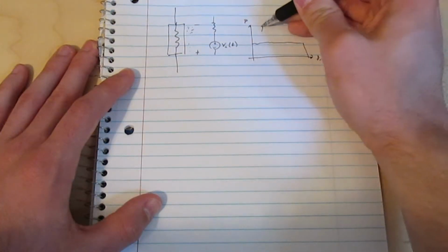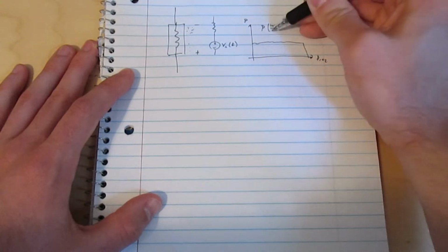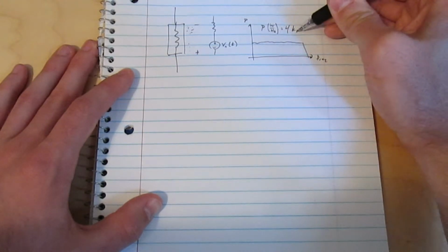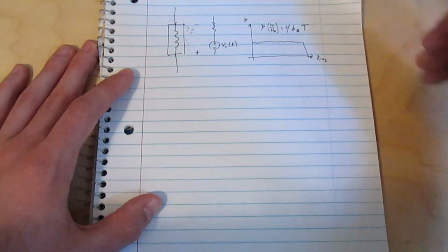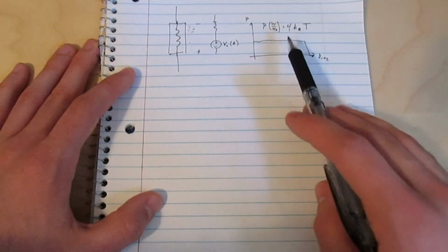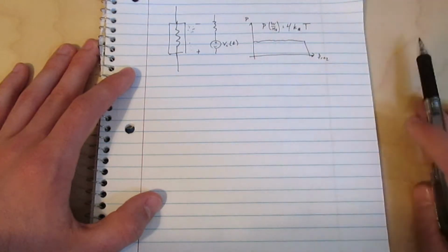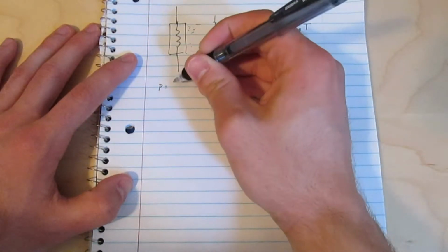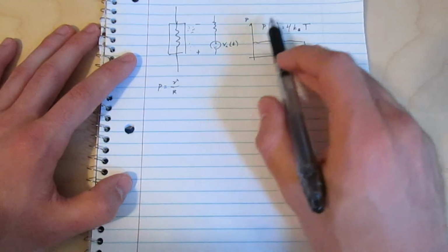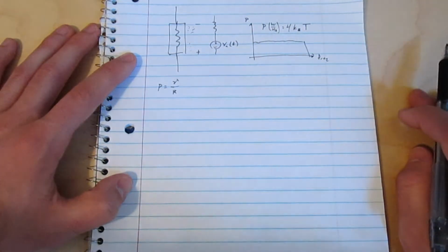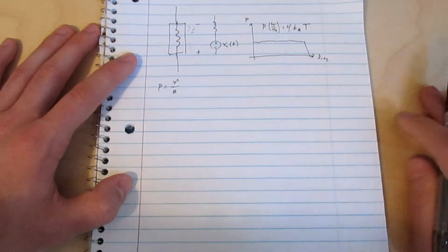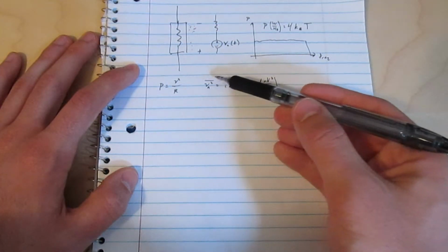And the power density in units of watts per hertz is given by the formula 4 times the Boltzmann constant times the temperature. Now exactly where this formula came from is kind of a long story, one that I forgot a long time ago, but there it is. Since the power dissipated in a resistor is the voltage squared divided by the resistance, we can plug this into our power density equation to get an idea of roughly what the noise voltage over a resistor is going to be. Now this bar above it right here means average.